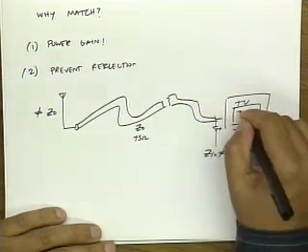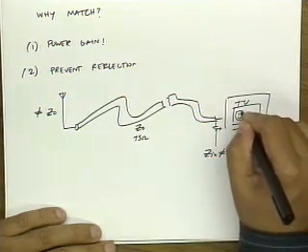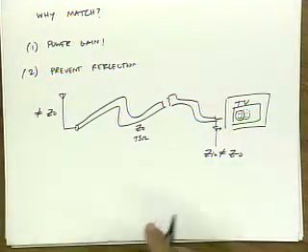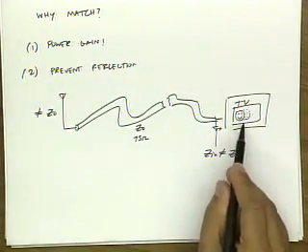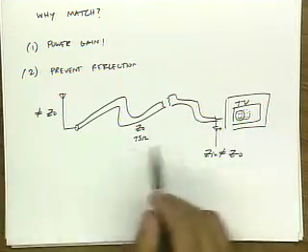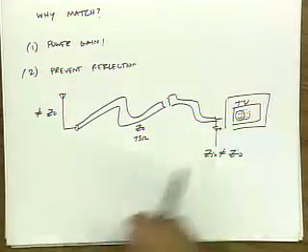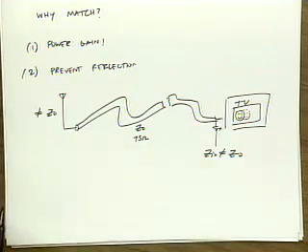So when the new signal arrives, what does it look like on the screen? It's a ghost, right? Because there's a time delay between the real signal and the reflection, you actually see a ghost. And since there are multiple reflections, you might see multiple ghosts, or a fuzzy ghost. Go try this at home. It's kind of neat. Introduce a mismatch and watch what happens on the screen.